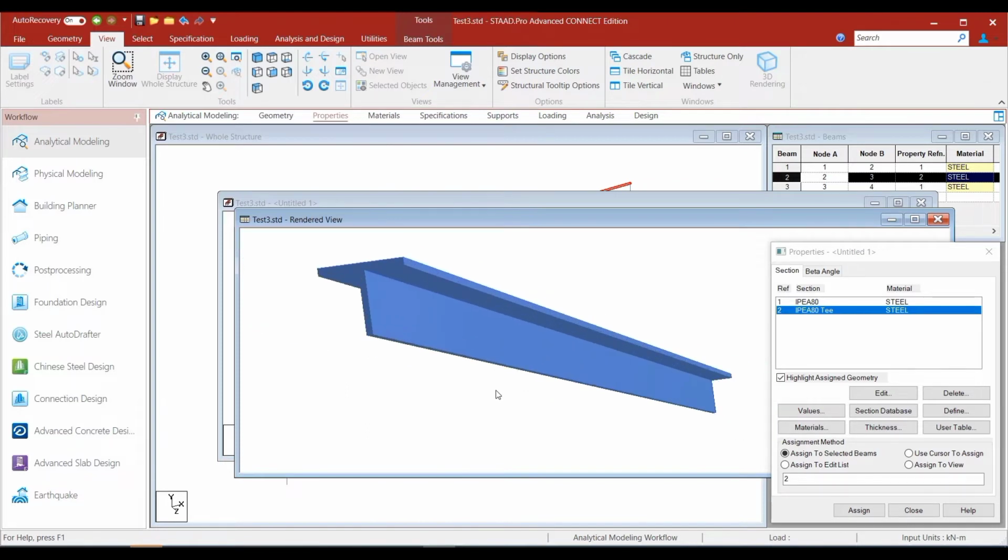as we had expected. Remember that the section properties of the T section would be calculated from the I section from which it is cut. For example, the cross-sectional area will be half of the I section from which it is cut. The moment of inertia would need to be calculated based on the centroidal axis of the cut section.